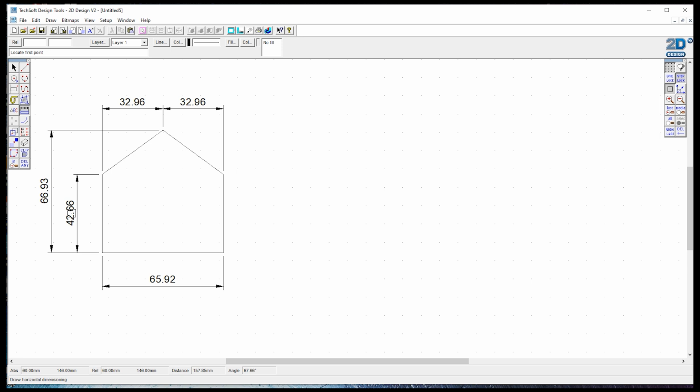So if I was going to draw something like this, this is how I would do it typically. And this works for most architectural projects where, generally speaking, we're dealing with horizontal and vertical measurements. So the first thing I would tend to do is switch on my gridlock tool, and as I showed you previously, we could quickly draw in a horizontal and a vertical line. Now these lines don't need to be accurate at the moment, I've just thrown them down to give me some reference geometry.